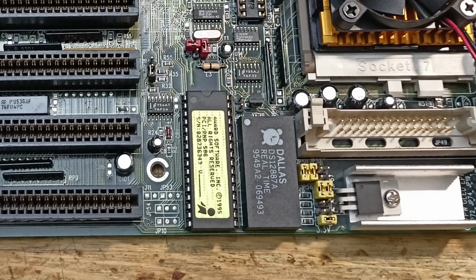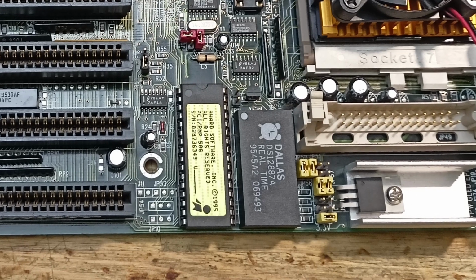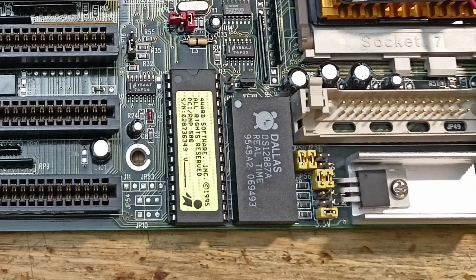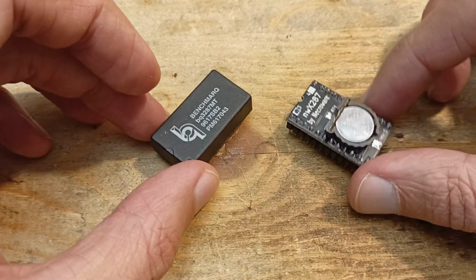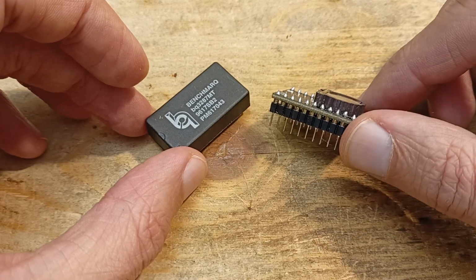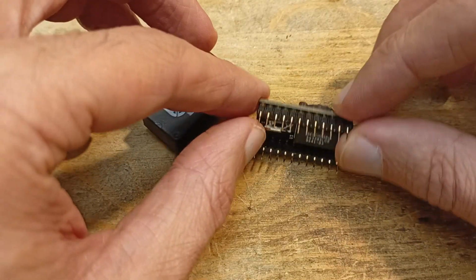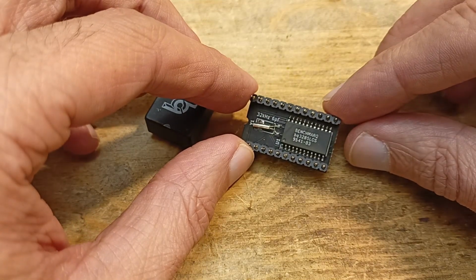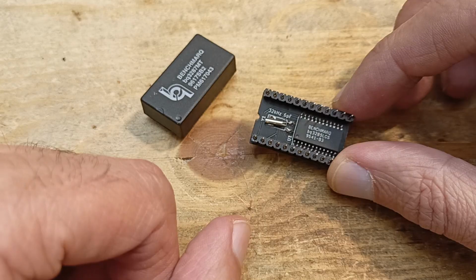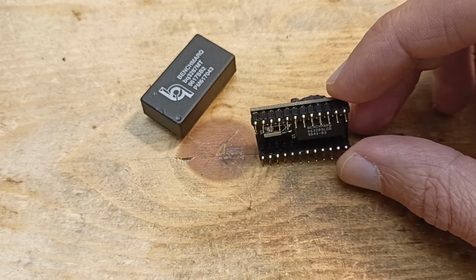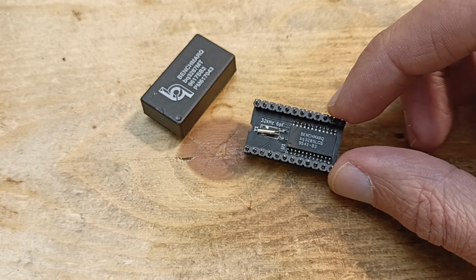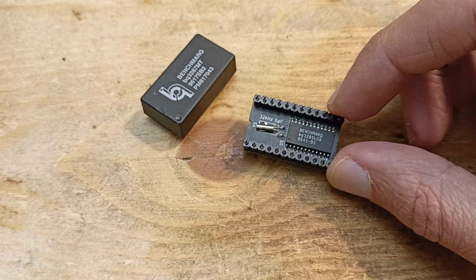Obviously, after 25 to 30 years, most of those RTC modules have already empty batteries inside, and today we have a lot of nice retro mainboards with a handicap. We needed an open source replacement, and so I introduced this solution, which was welcomed by the community very well. Essentially, this is the same module as the Benchmarq BQ3287 with a BQ3285 RTC chip, a crystal oscillator and a battery holder. As I open sourced this project, BQ3285 and compatible chips were not produced anymore, but there were plenty available as new old stock on known selling platforms.